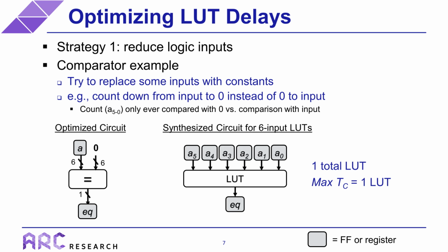So let's say we have this counting circuit and it needs to count some number of times, where that number is specified as an input that gets stored into a register. So it's basically a non-constant input. And let's also say that both the input and the count itself are both 6 bits. Now, one very common way of implementing this circuit would be to count from 0 up to the number stored in this input register. But if you do it that way, you end up with the exact comparator we just saw on the previous slide,